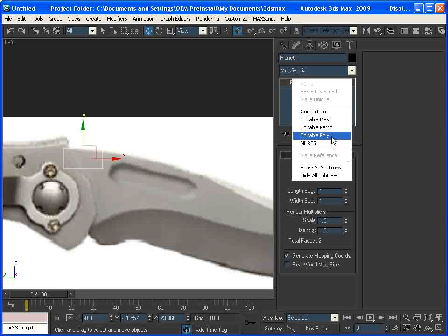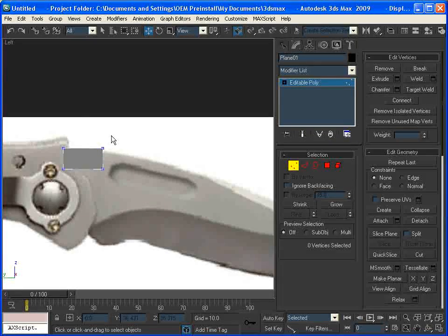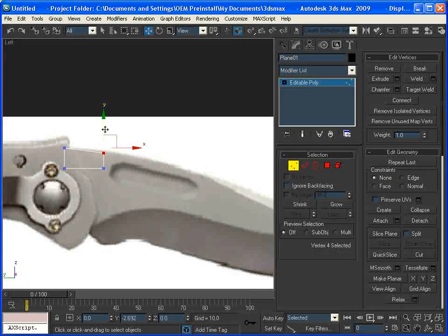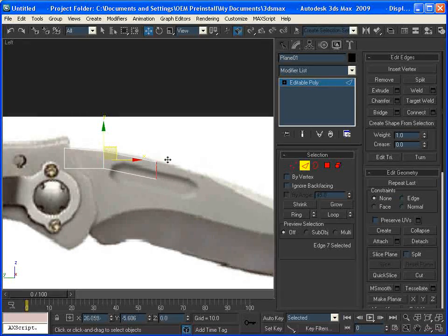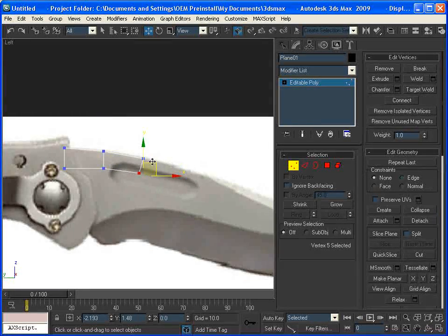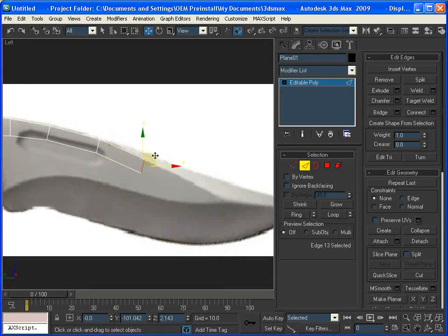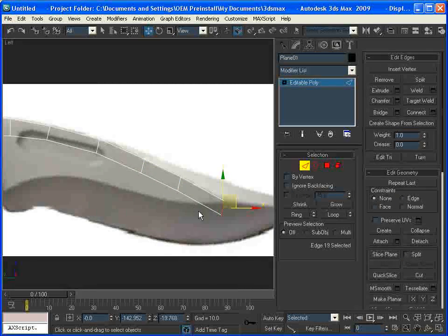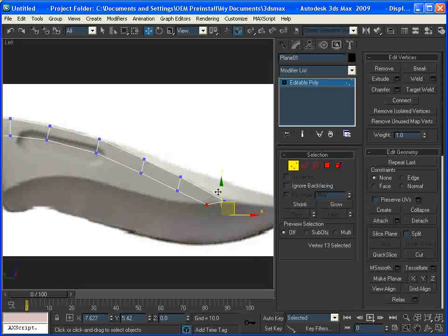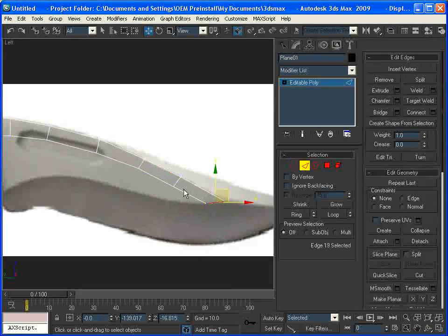So, the one important thing to remember if you haven't done a lot of high poly modeling yet is that it doesn't really matter what your poly count is. That probably seems obvious, because we're adding a Turbo Smooth or millions of polygons. We're not really being careful about the tri count. But sometimes, if you've done a lot of low poly modeling before you get into this, you're still working with the mindset that you need to create everything with the minimum number of edges and vertices and faces.